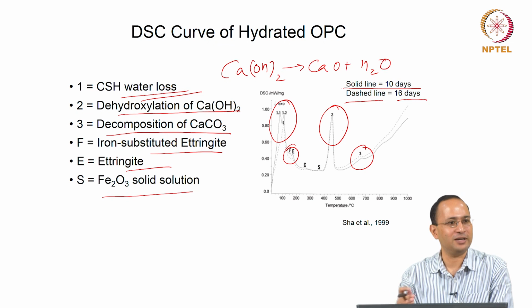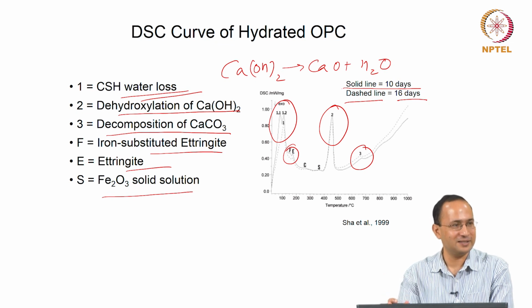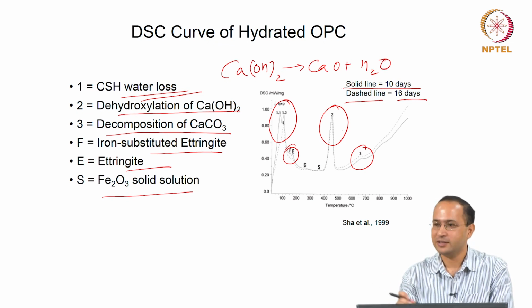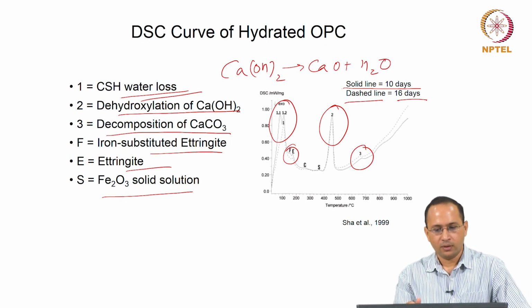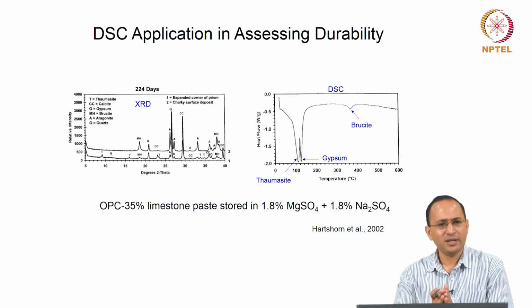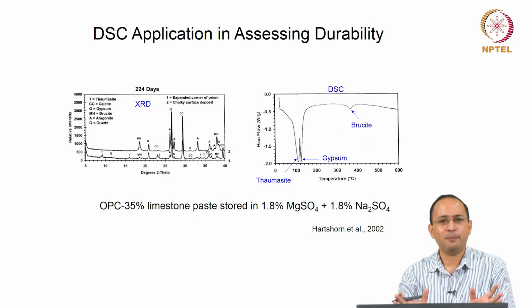Similarly, calcium carbonate decomposition occurs at a later stage, around 600, 700 degrees Celsius, where you will start seeing the decomposition of calcium carbonate into calcium oxide and carbon dioxide, okay. That is why again the point is to look at multiple techniques, you know, to get a better idea.